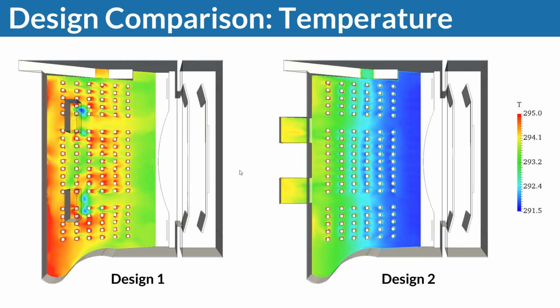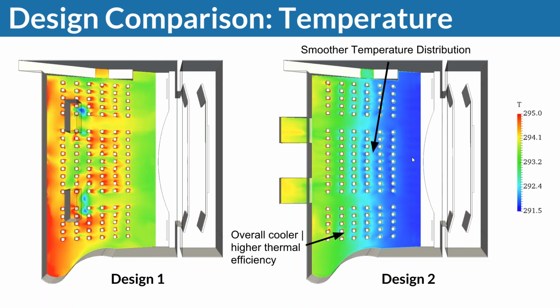Same view, temperature, right? We can see that on the left, the ugly piece was the blue regions directly below the air inlets. On the right, we've seen already with the ASHRAE 55 plot that the temperature distribution is very homogeneous, and overall, with the same amount of energy being used, we could cool the room more effectively. But the first rows might be a bit too cold, right? That's the one piece that we would still need to fix in a design 3. Unfortunately, we won't do that today, just to manage expectations here.